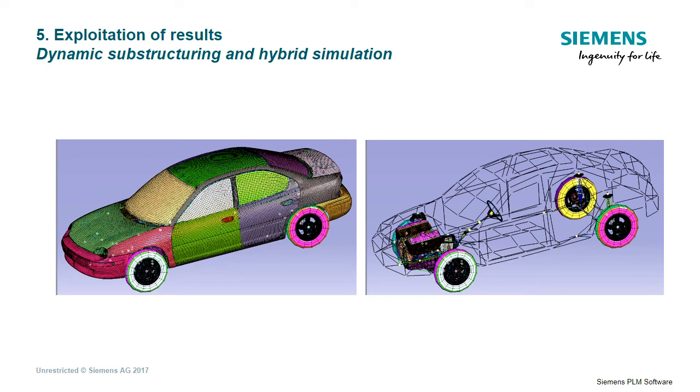The framework to combine component models to predict the coupled dynamic response is commonly known as dynamic substructuring. Within this framework, combining numerical and experimental components into an assembly for further calculations is generally known as hybrid modeling. A further step is then to run test-based simulations in which we can apply several load cases and predict the response of the assembly.